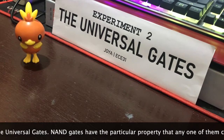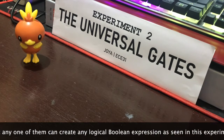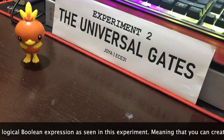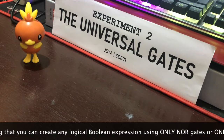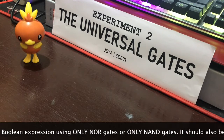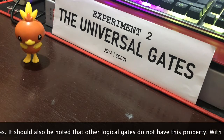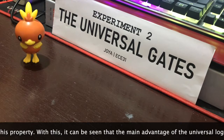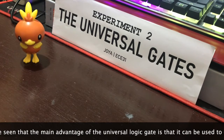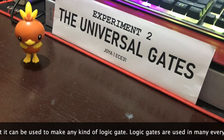NOR gates have a particular property that any one of them can create any logical Boolean expression as seen in this experiment, meaning that you can create any logical Boolean expression using only NOR gates or only NAND gates. It should also be noted that other logical gates do not have this property. With this, it can be seen that the main advantage of the universal logic gate is that it can be used to make any kind of logic gate.